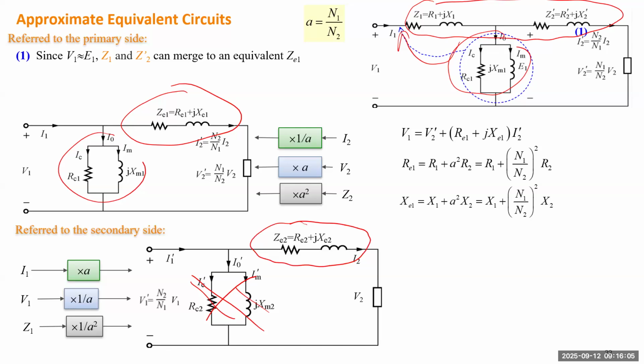This structure is very similar to the structure of any source, like a generator, right? In the generator, on the source side we have an EMF, an excitation voltage, which is connected to a synchronous reactance and also the armature resistance. Then it can power the load of the external system. So now we have a structure very similar to the equivalent generator circuit.